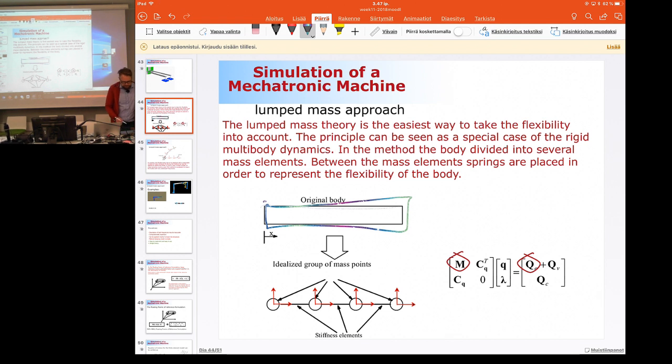What you do is break this rigid body into a number of rigid bodies. Say that the initial rigid body is divided into 4 rigid bodies like shown here. Then afterwards you introduce spring elements in such a way that there is a stiffness in all 6 degrees of freedom with respect to the neighboring rigid bodies. So there will be spring elements, axial spring, torsional spring, such that it behaves as a rigid body.